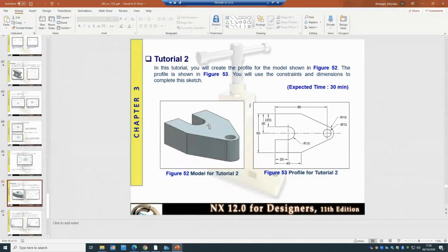Again, you might say, I want to do it differently. You might say, I don't want to have that circle in the middle. So what you need to do is, once you extrude it, then you cut these. Or you extrude everything and you cut this one and cut that one. Technically, you're doing two more features. But that was the simplest and easiest way we could do it within a short period of time.